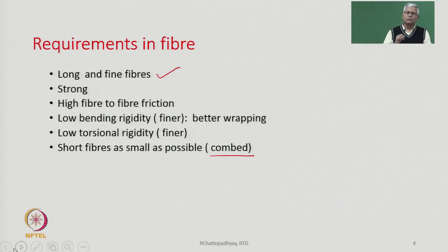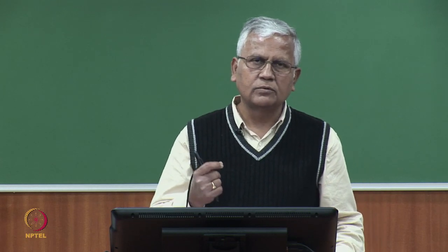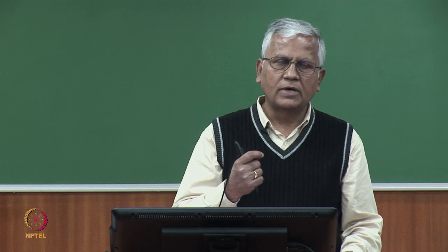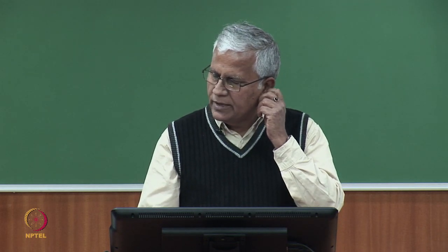Because some of the fibers will be utilized to wrap the core, fine fibers are better because fine fibers will have less bending rigidity in comparison to a coarse fiber. Second thing is that if the fiber is long, the friction is going to be more. So, many a time the yarn may break because of slippage between the fibers.